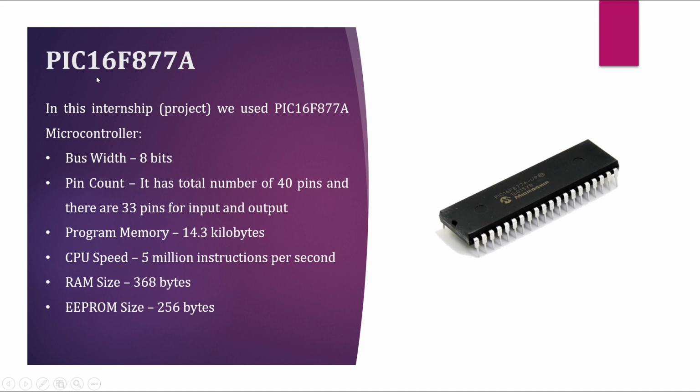So coming to the microcontroller which we have used, that is PIC16F877A. In this internship project, we have used this particular microcontroller. If we see the specification of this microcontroller, the bus width is 8 bits. Pin count, it has a total of 40 pins, and there are 33 pins for input and output. Program memory, 14.3 kilobytes. CPU speed, 5 million instructions per second. RAM size is 368 bytes. EEPROM size is 256 bytes.